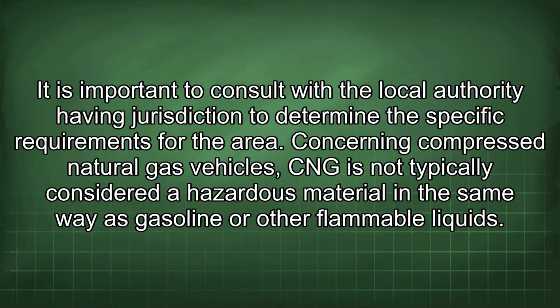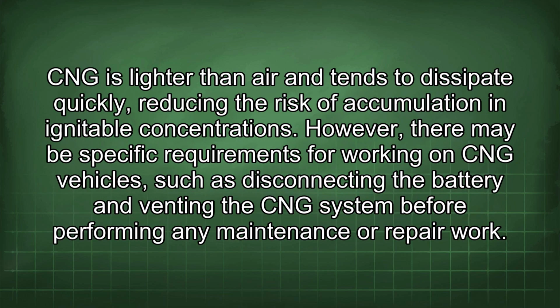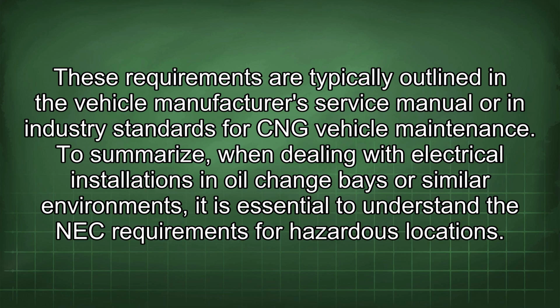Concerning compressed natural gas vehicles, CNG is not typically considered hazardous material in the same way as gasoline or other flammable liquid. CNG is lighter than air and tends to dissipate quickly, reducing the risk of accumulation in ignitable concentrations. However, there may be specific requirements for working on CNG vehicles, such as disconnecting the battery and venting the CNG system before performing any maintenance or repair work. These requirements are typically outlined in the vehicle manufacturer's service manual or in industry standards for CNG vehicle maintenance.